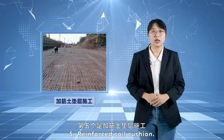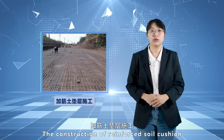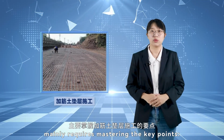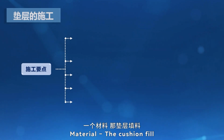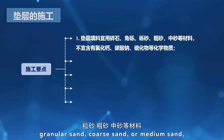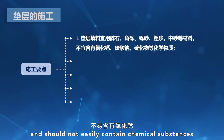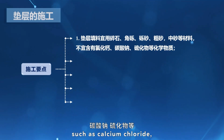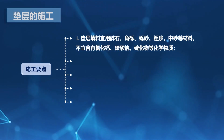5. Reinforced soil cushion. The construction of reinforced soil cushion mainly requires mastering the key points. Material. The cushion fill should preferably be crushed stone, rubble, granular sand, coarse sand, or medium sand, and should not easily contain chemical substances such as calcium chloride, sodium carbonate, or sulfides.